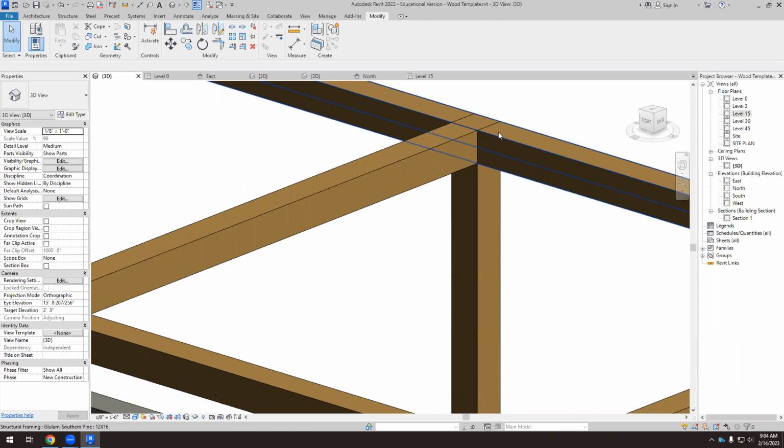This bucket element is something that is bolted to that beam here. And at the same time, we create like a bucket. It's an element that is a U, and on that U we rest the beam. The elevation is something like this: we have a U, and we have these two plates.